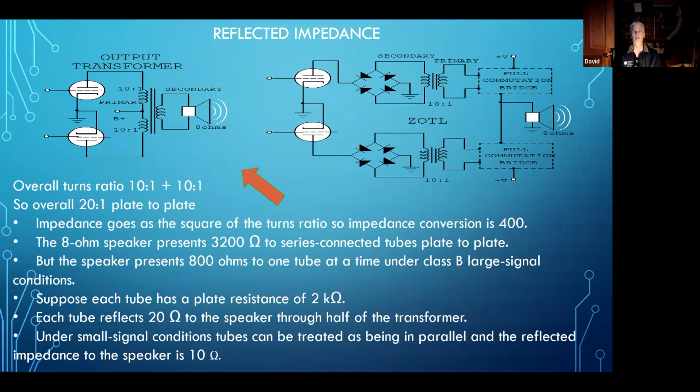There are speaker crossovers. There's back EMF, back electromotive force, and stuff like that, which can put power back into the amplifier that's driving it, out of phase with what you think you're trying to drive it with.